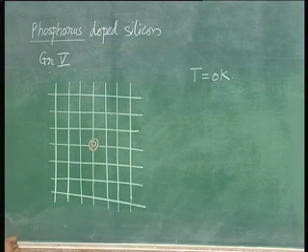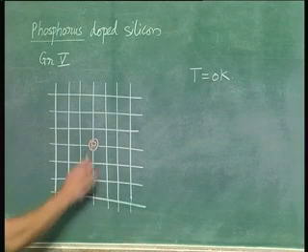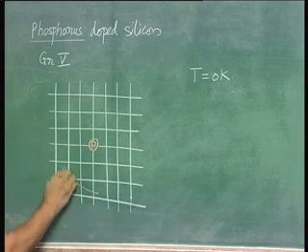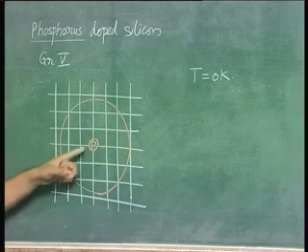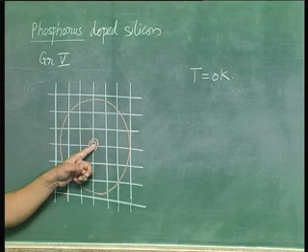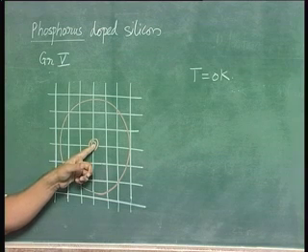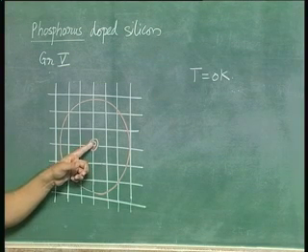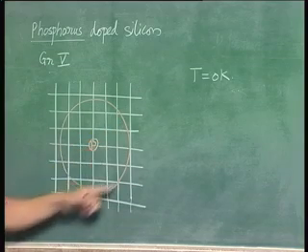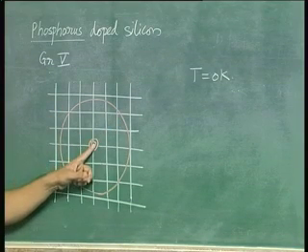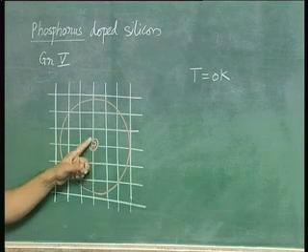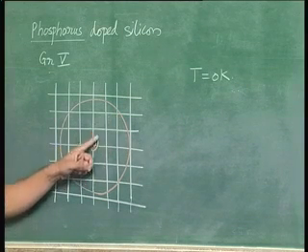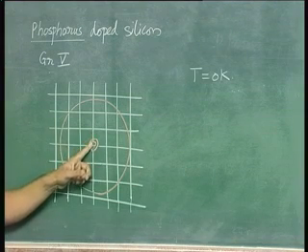A simple model says that the 5th electron will simply revolve around this phosphorus atom, just as you have the picture of a hydrogen atom where there is a positively charged nucleus and an electron orbiting around it. Notice that since phosphorus is a group 5 impurity, it has 5 electrons in the outermost orbit. So without this particular electron, the phosphorus atom is positively charged.